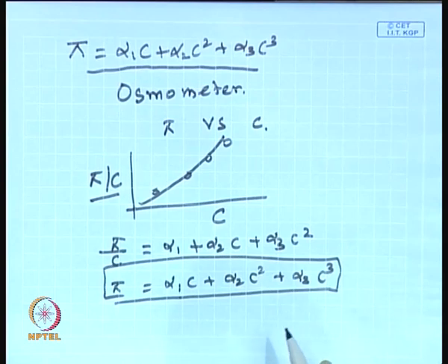Now, for membrane based processes, the osmotic pressure becomes very important. Why? Actually any solution will have its own osmotic pressure. For example, if we have a glass of saline solution, or let us say sugar solution, or a cane juice solution, it will have its own osmotic pressure. But you cannot realize the osmotic pressure. Why? Because osmotic pressure can be realized if and only if a semi-permeable barrier is present in the solution. Otherwise, you cannot realize the presence of osmotic pressure.